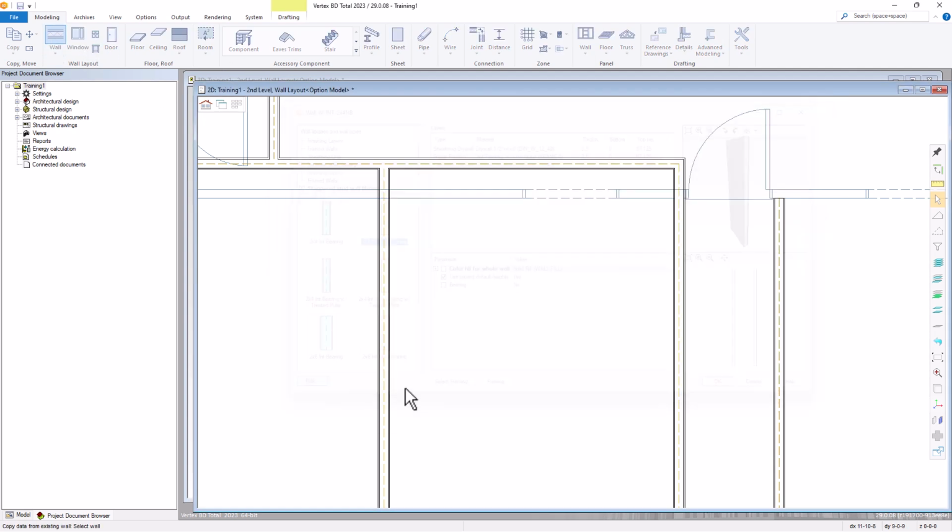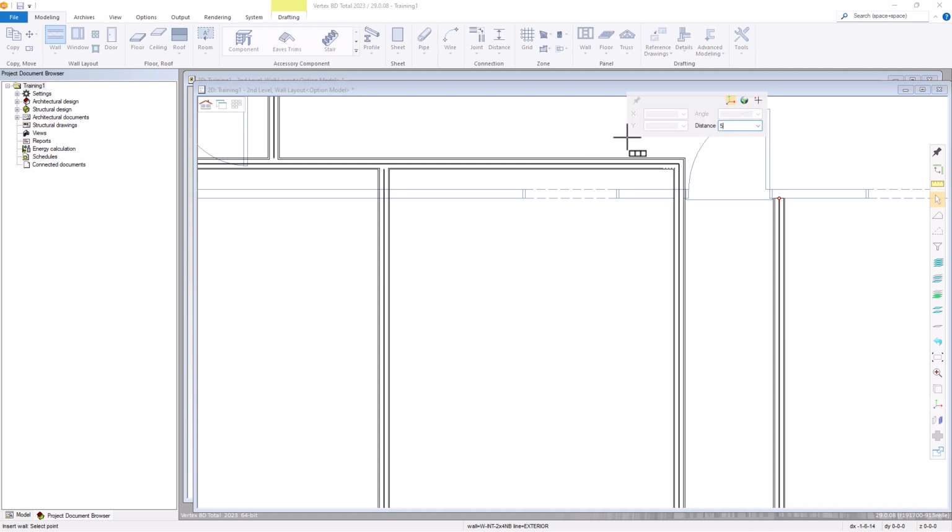Let's select pick and just click any one of the walls that you've drawn so we select the same type of wall. Come over to this corner, cue off that corner, hit U. The interior width of the closet is 5 foot 4.5.